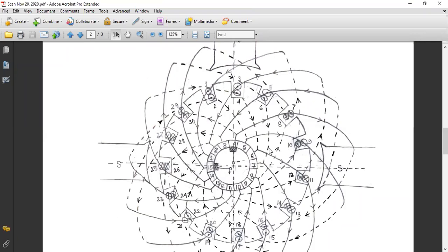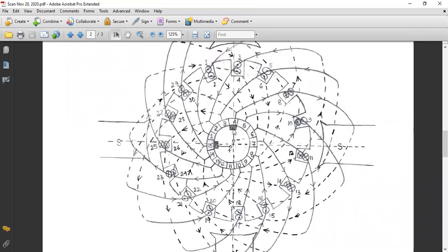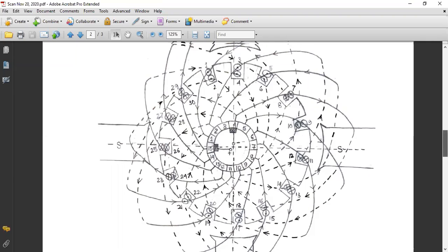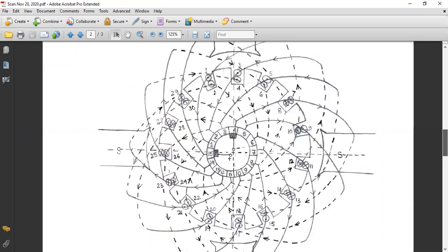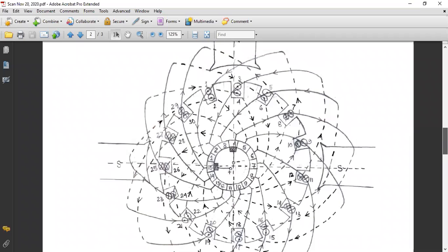So here, he has placed one brush at 4, because you see at this commutator segment 4, two coil sides are connected and two coil sides are carrying the outgoing current. So he has perfectly placed the brush at the commutator segment 4, no question in that. Now all these currents are outgoing, so we have to search for another position of the brush where both the currents are incoming. So if you see where both the currents are incoming, you just check it, where we are getting that both the coils are incoming.